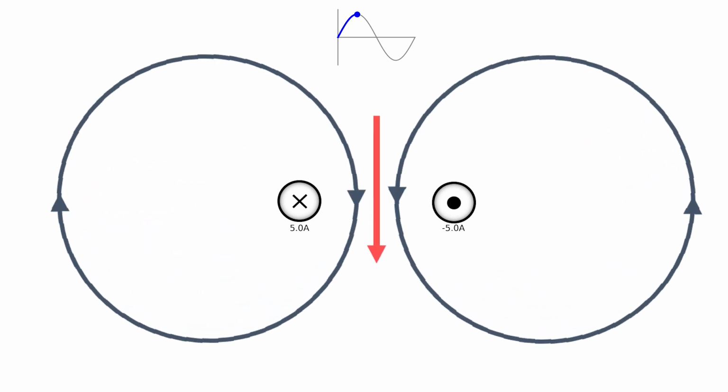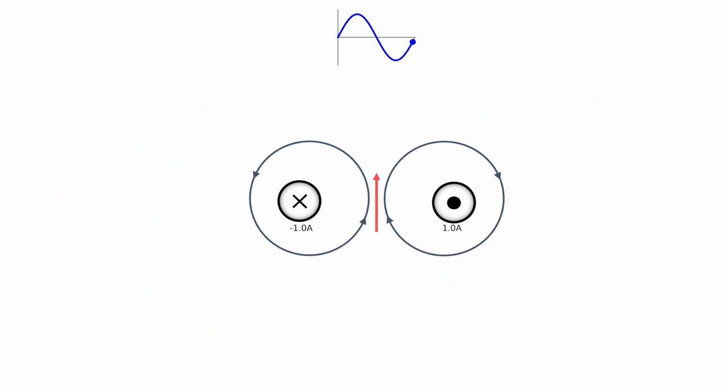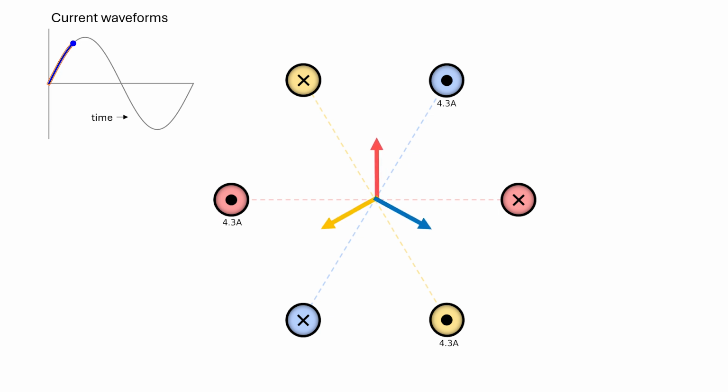Remember how we passed a sinusoidal current through the coil to generate an oscillating field? If we pass a similar sinusoidal current through our earlier arrangement of 3 coils, each coil sets up its own oscillating field. As you can see, these oscillating fields vary in phase with each other, canceling each other out at every instance of time. The net field generated in this case is 0.